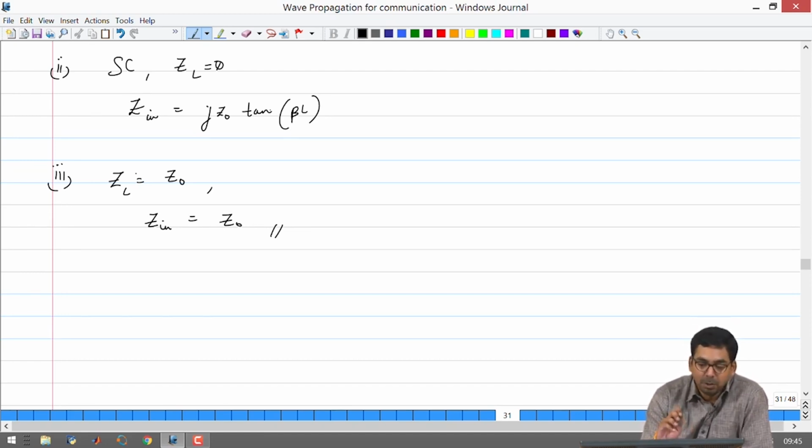So, the only way to go forward is to actually introduce a different phenomenological model. So far we have been using a lossless transmission line with L and C. We have to be a little bit more practical, include a series resistance in the inductor branch, include a parallel conductor and redo whatever we have done, and then we have to see what the consequences would be.